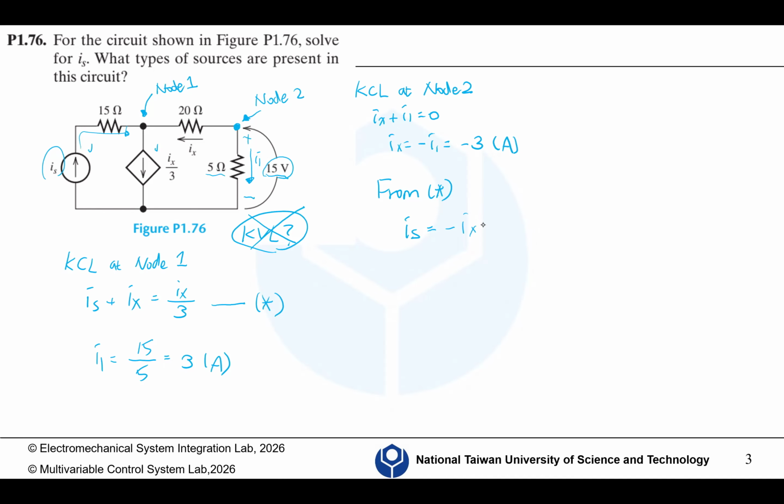Starting from the bottom left corner, we have minus 20, plus 4 I1, and so we keep going, plus 6 I2, and then plus 2 I2 equals 0. So we have an equation of I1 and I2, but we need another equation.